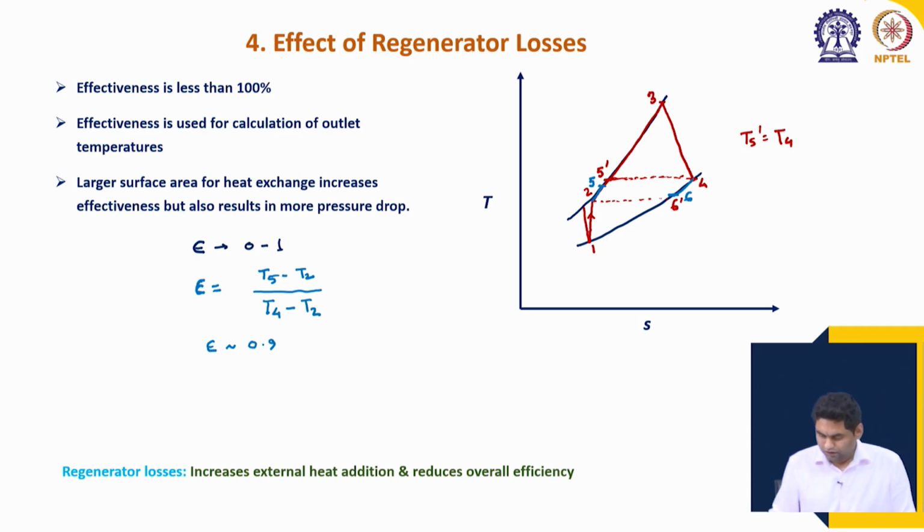More accurately, if we have variable Cp values, as we will see in the next slide, then accordingly we have to do the energy balance. If the Cp of air and Cp of gas are considered different, which we will do from the next slide onward, and if the mass flow rates are different, which also will be the case later on, because the mass flow rate at the air side is equal to the inlet mass flow rate m dot A, while at the gas side the mass flow rate is higher, which can be called m dot G, equal to m dot A plus m dot F. So, the mass flow rate of fuel is also added in the combustion chamber.